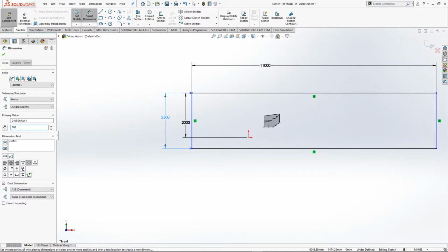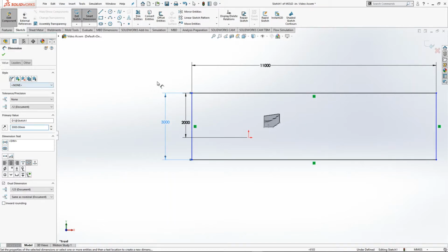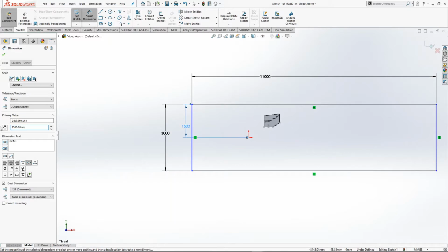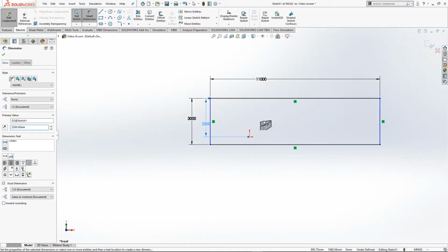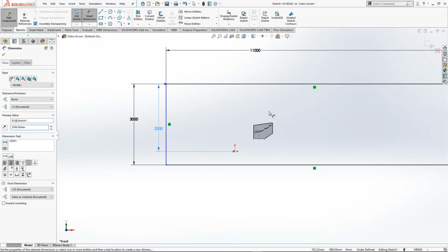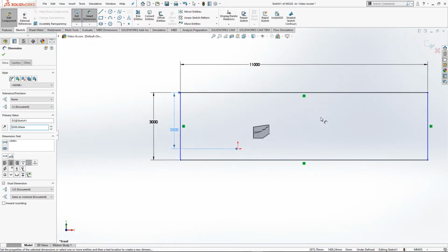and just create a boundary box which is suitable for the part that you're doing. Oh, I want to increase that actually. So for this wing, we don't need a whole lot of area in front of the part. However, we want a lot after to see what the flow does behind the part.